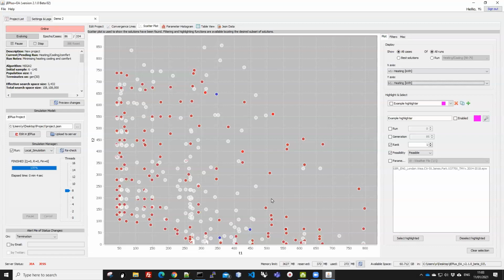If you imagine the entire array of outcomes as populating a 3D space, then the Pareto front will be almost like a slice of orange peel, close to the origin in 3D. So if you project it onto a 2D plane that is heating and cooling, you'll get something like this.